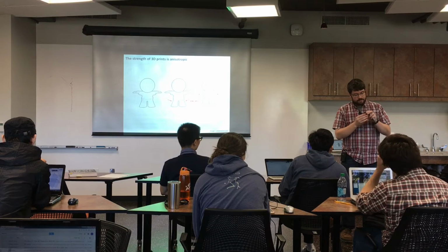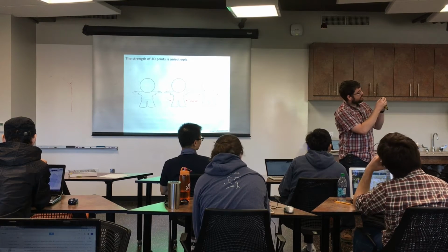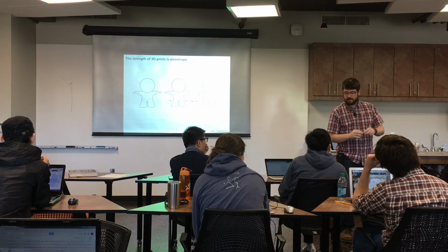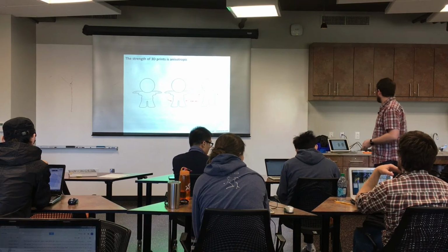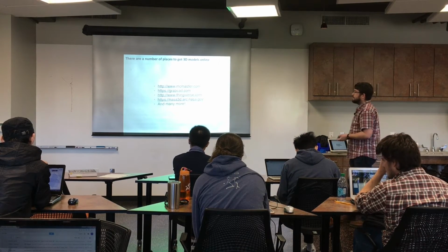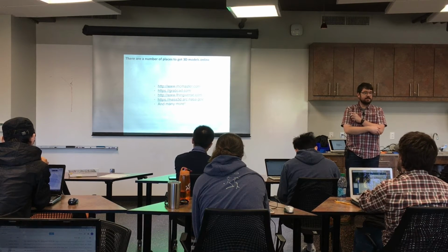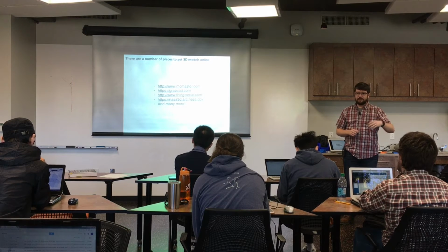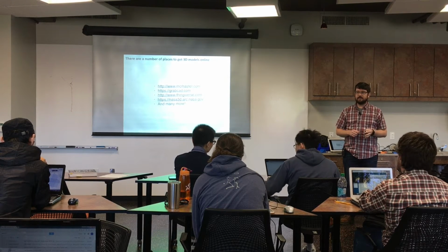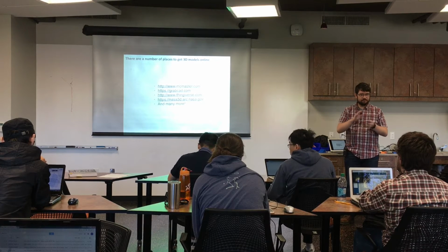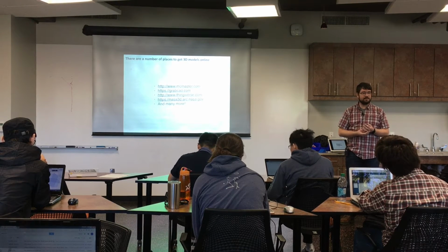And you can see as it was printed, sitting with this end up, there's a little bit of droop in these holes, but not much. And that's something that you should specify when you send your print. If it needs to be printed in one orientation, they have an undergrad working at the library that is going to take his best guess at what you meant for your part to be. But if there's something specific, you should tell them.